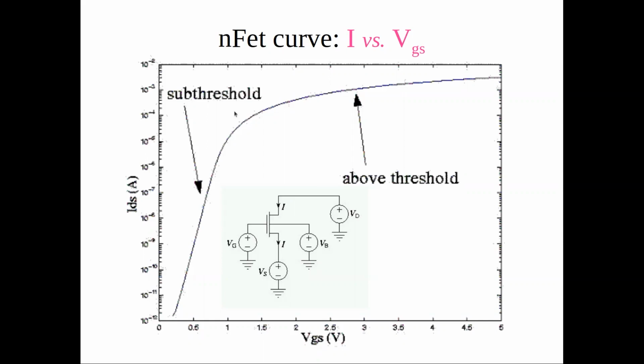Okay, maybe another. So this is the current from the source to the drain on the surface, independent of the thickness of the depletion region. This is really how much current flows because of the diffusion and of drift, on the surface. And what I'm plotting there is the capacitance, which is not current, as a function of the gate voltage. So the x-axis is the same, but the y-axis is different.